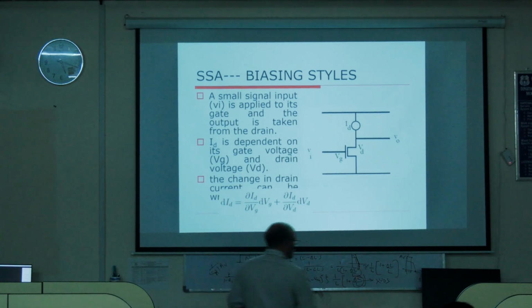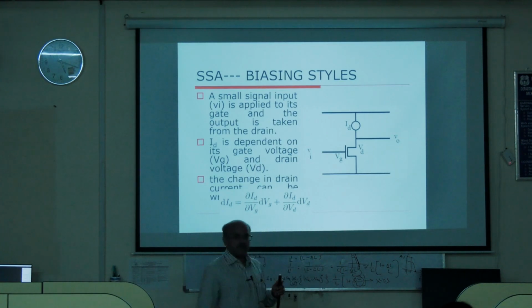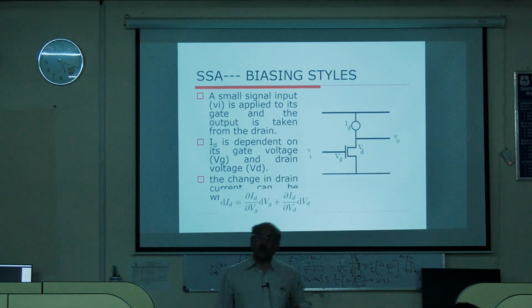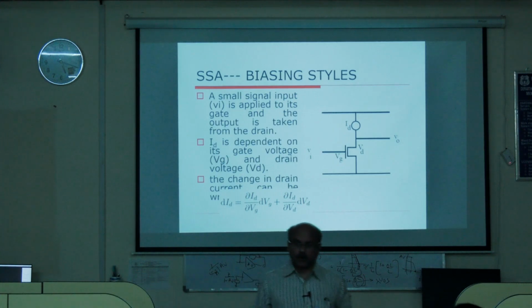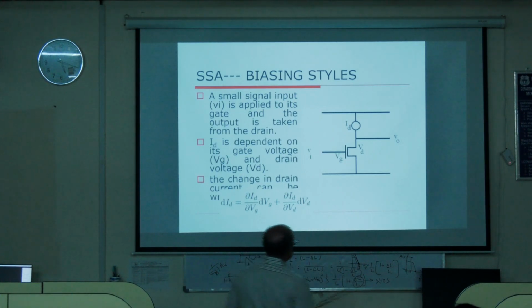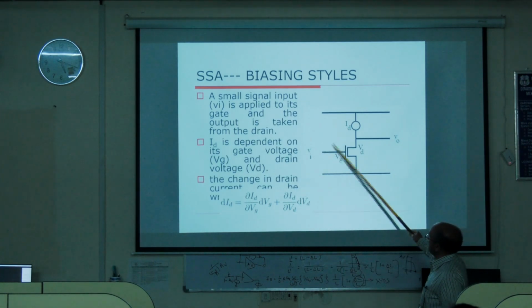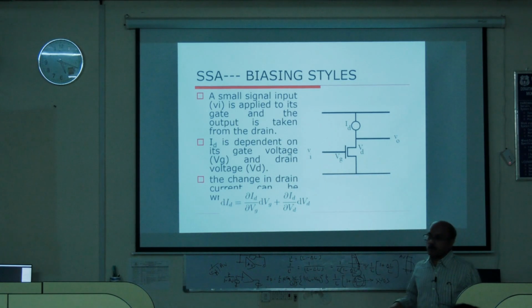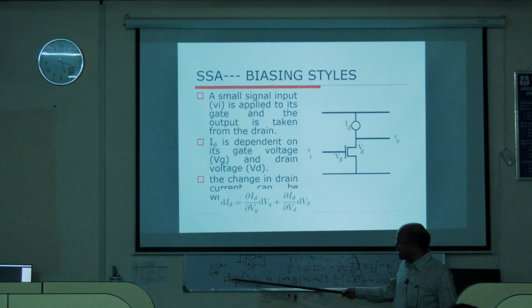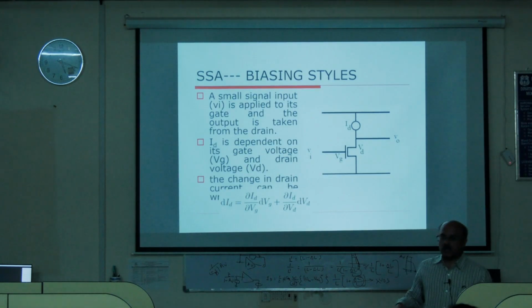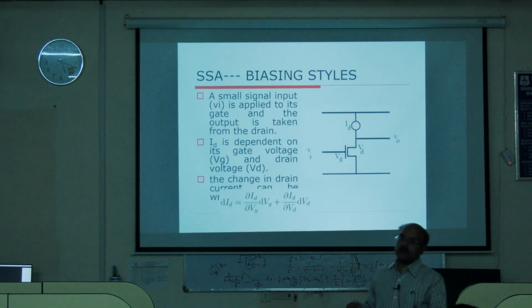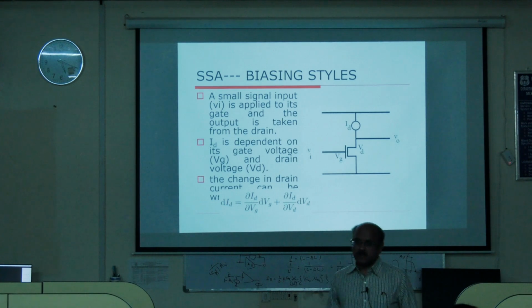So whenever there is a problem, if you want to look at the solution, then immediately what we have to look at is who is the culprit, who is causing the problem, right? The culprit is this fellow. This capacitance between the output and the input, the capacitance CGD, is there, right? So that fellow, due to Miller, is getting multiplied by gain terms actually. The larger the gain, the larger you are increasing W, and therefore the larger the C, and therefore C is getting even multiplied by gain terms.